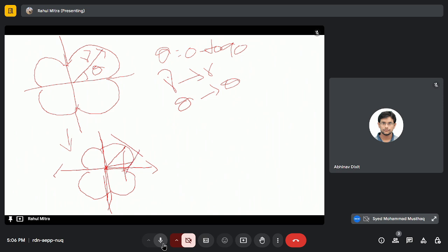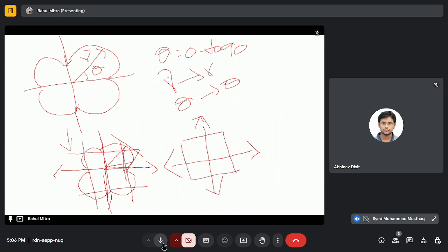Where the surface energy, or gamma, is minimum, there the tangents will cut most of the tangents. So if I draw the tangents at those points, it will become a cube. So from the polar diagram, we define our equilibrium shape of the particle. This is called the Wulff diagram.